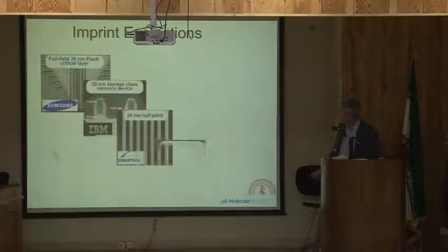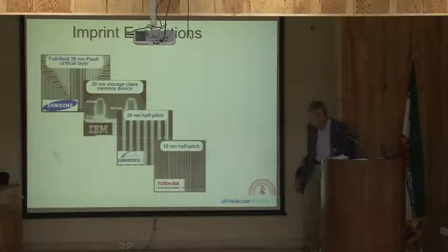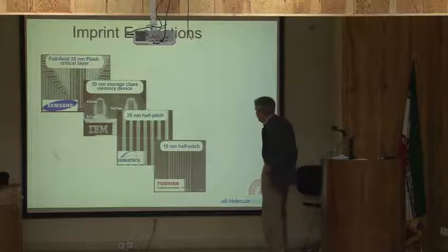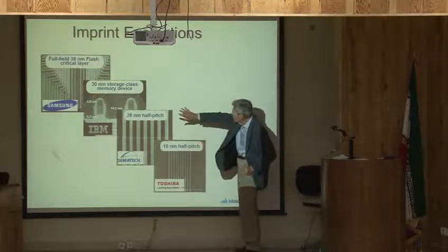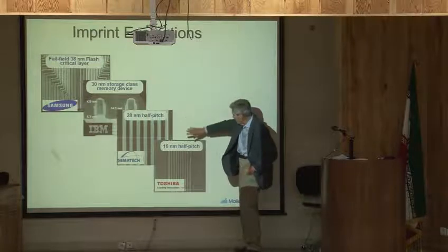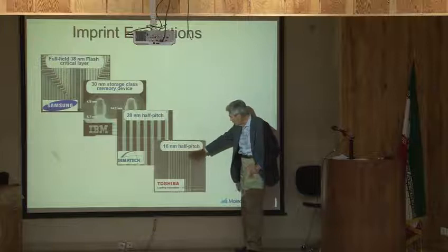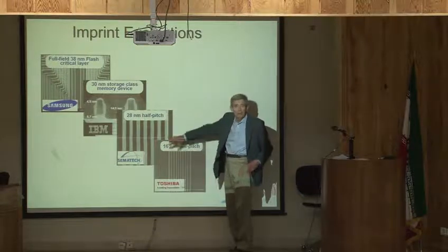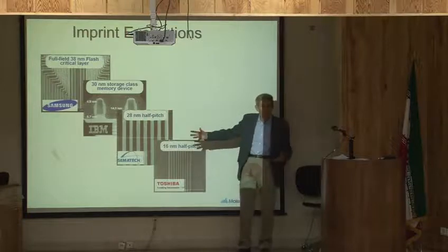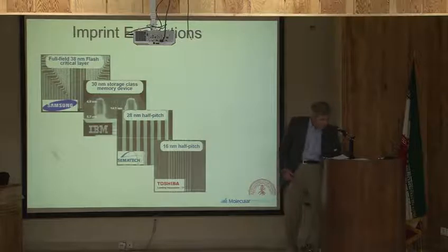Yes, here we go. So these are some imprint features. And these were done on what is now a commercially available machine. Again, just squashing. They've got features here of a 16 nanometer half pitch. You can say it's pretty good line width control. The EUV people would, I don't know if you understand the word, drool if they could do this. And just as a